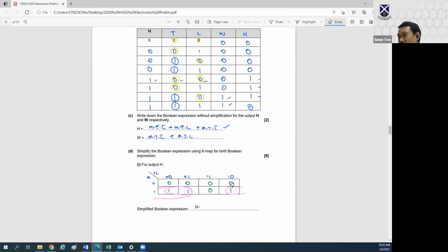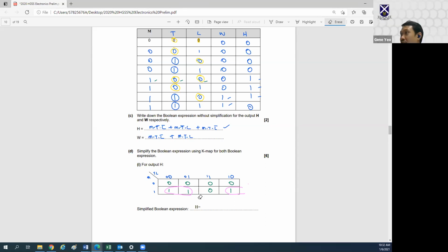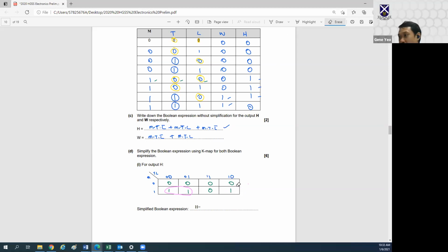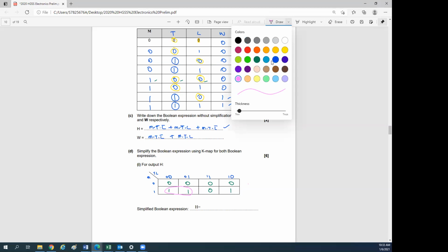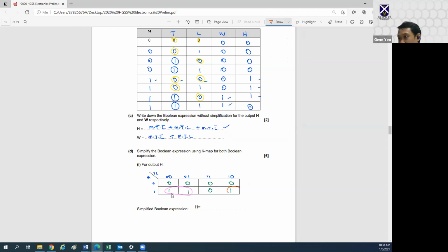Let's ask Kiran. Kiran, what did I do wrong when I grouped this with the other two? You grouped in 3. You can only group in 1s, 2s, and 4s. Excellent. Very important to learn that you only group in 1s, 2s, or 4s. You can't group in 3s. Okay, Ashwin, got it? Awesome. So now the correct grouping is this one and this one. I'm going to settle the pink one first.